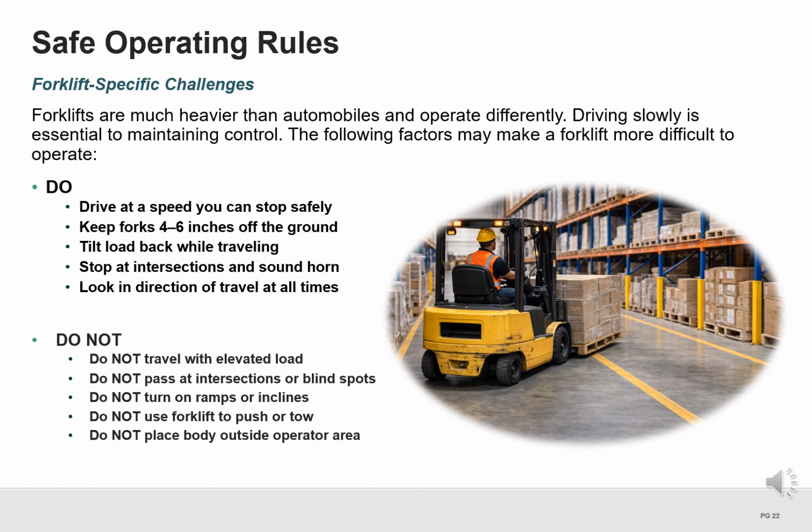Forklifts operate differently than automobiles and require greater control and awareness. Always drive at a speed that allows you to stop safely. Keep your forks low and tilt the load back while traveling. Stop at intersections, sound your horn, and always look in the direction of travel.